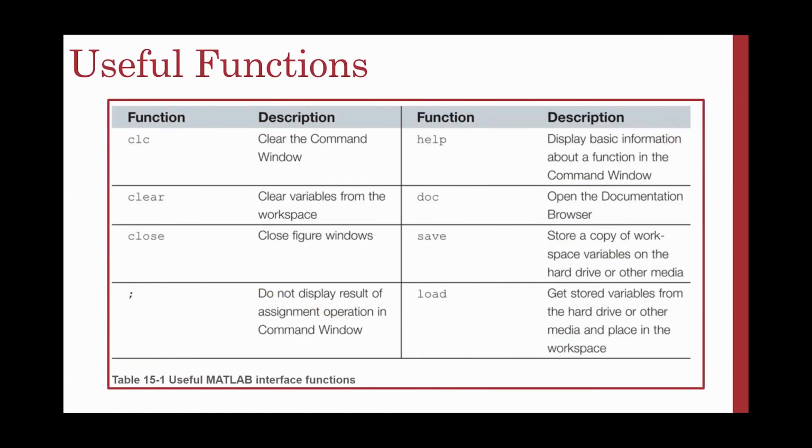So some useful functions in MATLAB. Again, clc clears the command window. Clear clears all your variables in your workspace. Close will close all figures. Putting a semicolon after a line of code will not display the result of the operation in the command window. So if you have a lot of steps to a problem that you don't necessarily want to print, you want to suppress them with a semicolon.